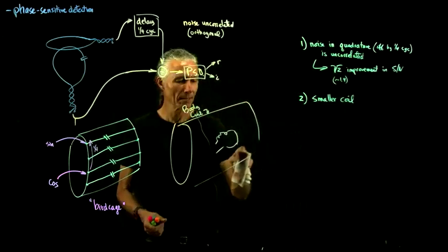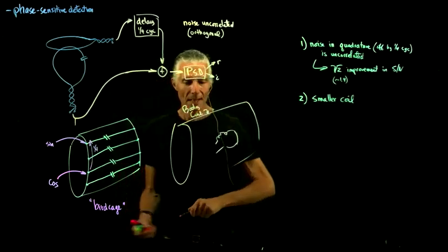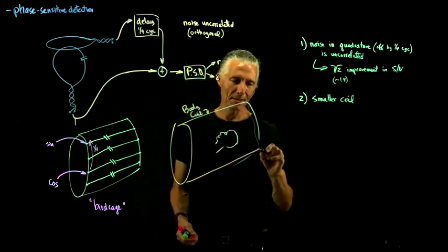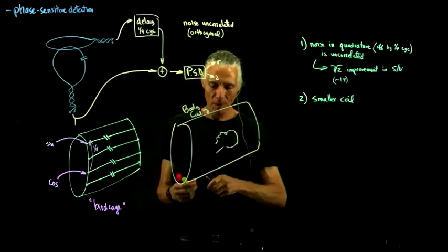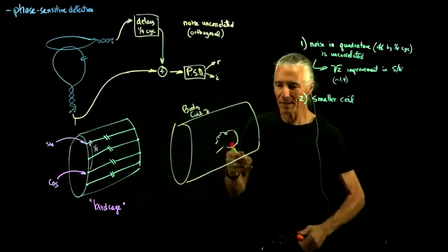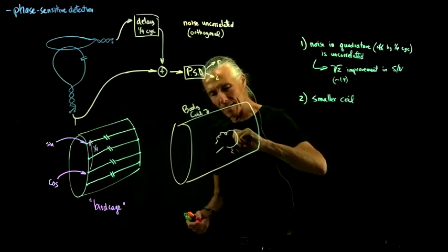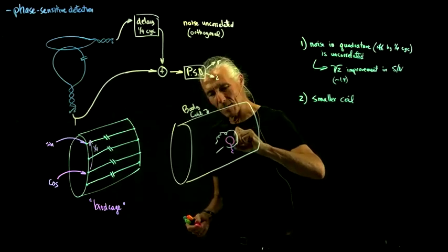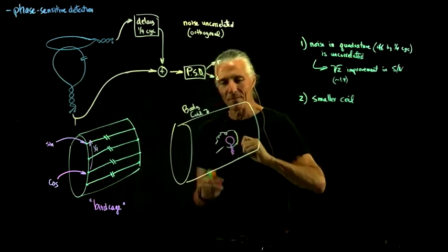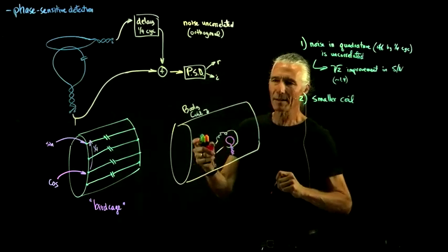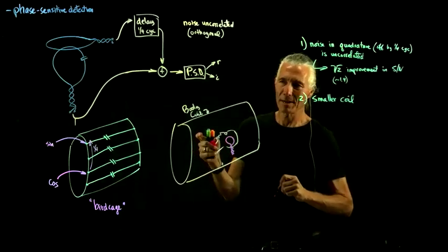The signal to noise isn't very good. And why is that? The reason is, it's a great antenna. It's a much better antenna than a smaller coil, like this. If you put a little small coil next to the head like that, this guy is going to actually be a better antenna. And why is it?